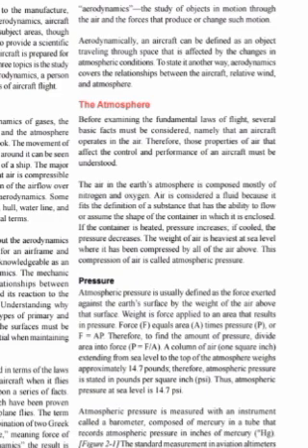Pressure equals force divided by A. A column of air, 1 square inch, extending from sea level to the top of the atmosphere, weighs approximately 14.7 pounds. Therefore, atmospheric pressure is stated in pounds per square inch, psi. Thus, atmospheric pressure at sea level is 14.7 psi.